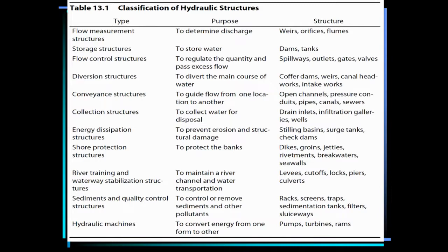If we have a channel dug in soil, definitely we will have sediment. And sometimes the sediment can come from other sources, not from the channel itself, but from the environment, because when water is washed from the surface of the catchment, it will all end up in the drains and carry the sediment. When the sediments are inside, they can deposit. Depending on the volume, if they deposit at the bottom, they will reduce the effective size of the channel, and that will affect the flow of water in the channel.